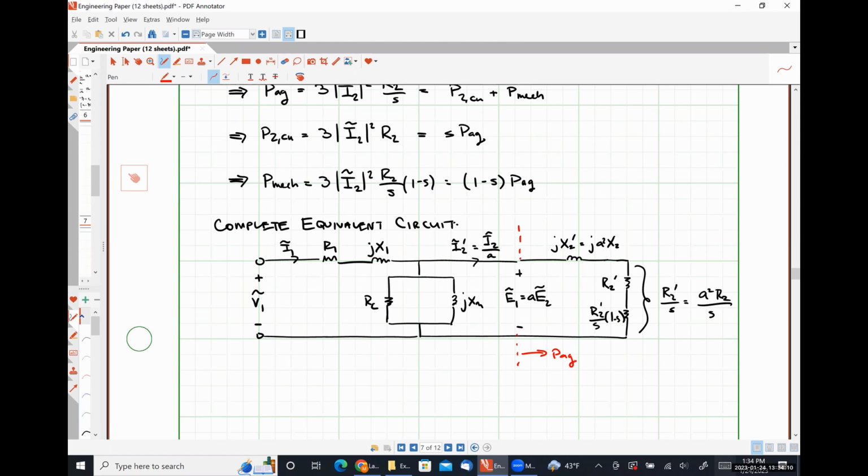The reason is, if you recall, we were able to lump all of our leakage resistances and reactances together because our magnetization current was small, typically between 1 and 5% of our primary current. Our magnetization current in an induction motor is going to be 30 to 50%. So effectively, we can't just move that shunt stuff over to the primary terminals and call it a day. So we're going to use Thevenin equivalent circuits in order to make our life a little bit easier.